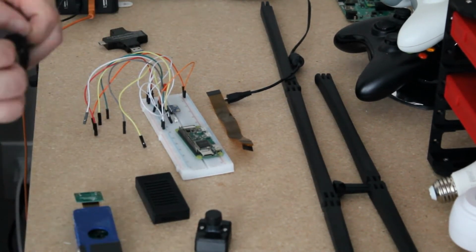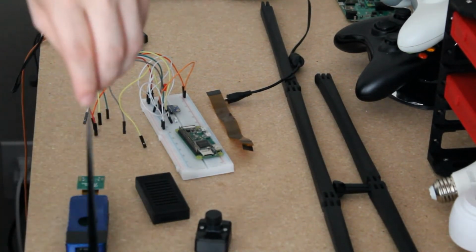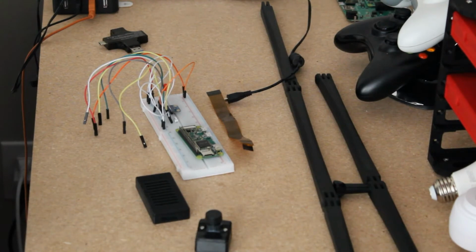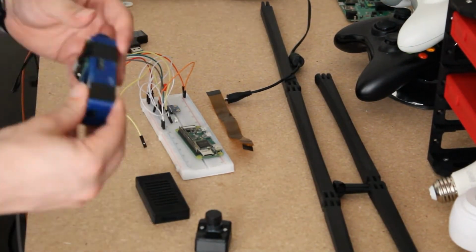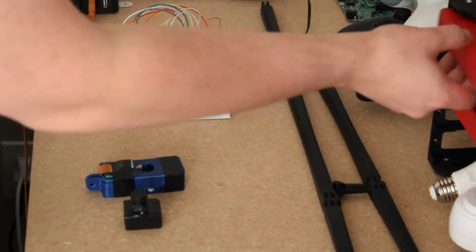But, like I mentioned in my previous video, there is a possible solution. By soldering a connecting wire between the ground on the PCB and the HDMI plug housing, we can fix that missing ground and allow the cheaper HDMI cables to work. So now it's time to test out the video and see how it works.